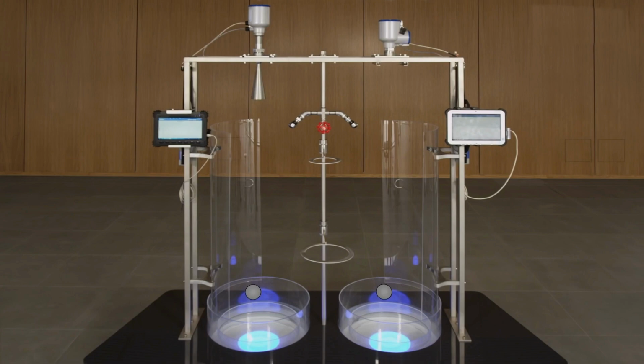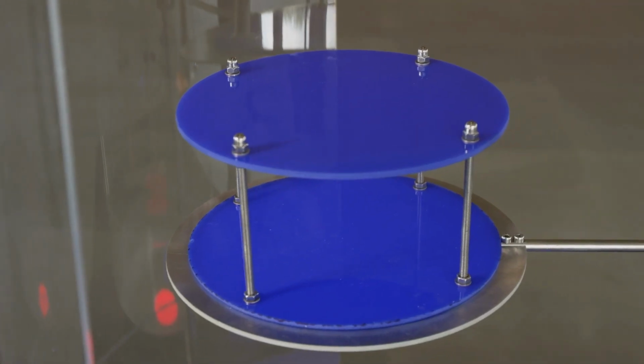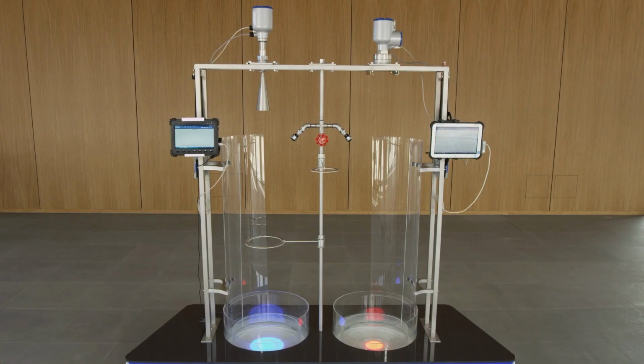The bandwidth of a radar system determines, among other things, the distance resolution of the system. Clearly, this means the higher the signal bandwidth, the better the distinction of two mutually close reflections, and thus, for example, the separation of the product surface from interference reflections. By observing the reflections on a double plastic plate, this effect can be demonstrated.